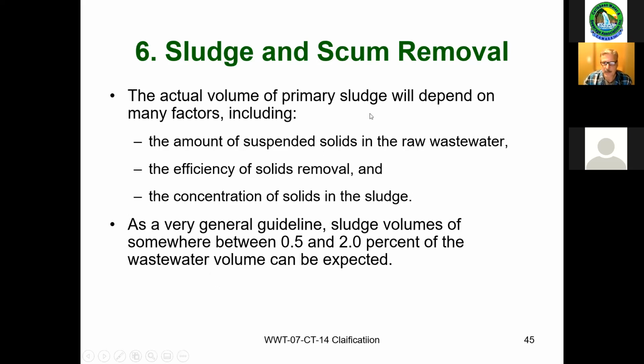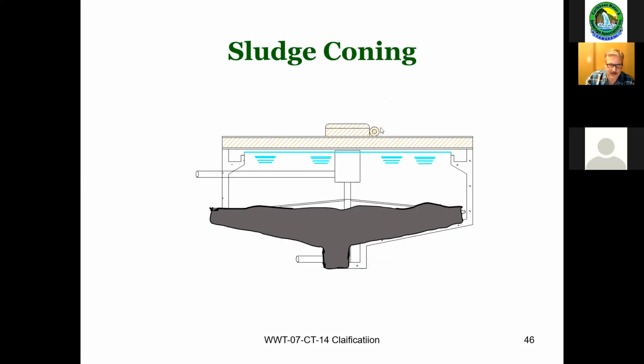Scum removal. Again, scum removal is typically done at least on a daily basis. A lot of times it's a manual operation. Pretty straightforward. I'm assuming that you, as operators, are removing the scum from your primary clarifiers.